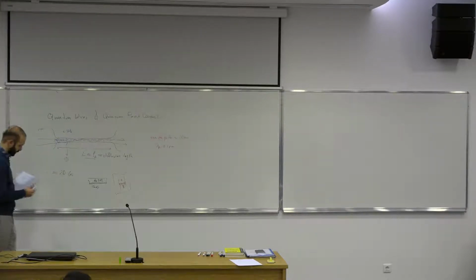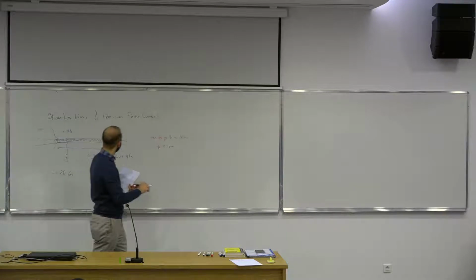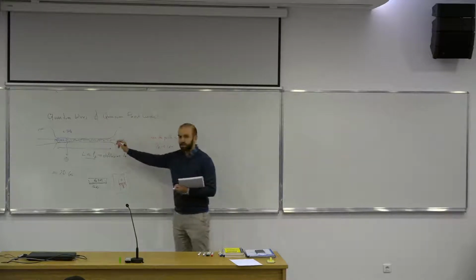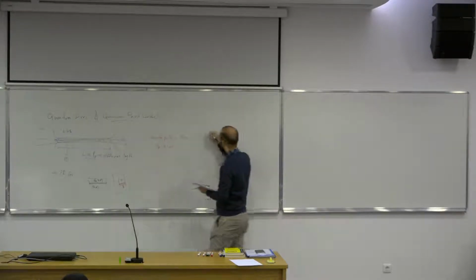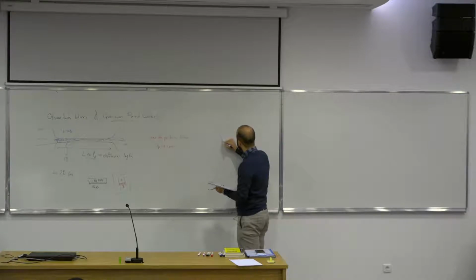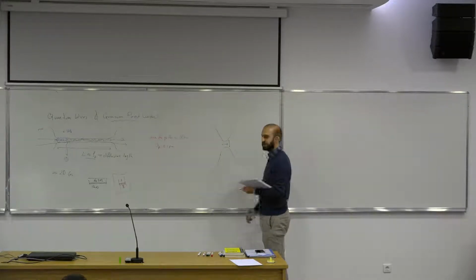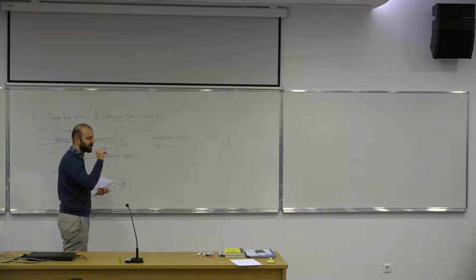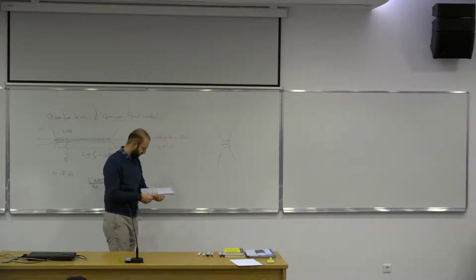So another object that I'm going to talk about is quantum point contacts. That's very relevant to sending electrons into a quantum wire. Actually, we are going to spend most of our time discussing quantum point contacts. And the idea there is you have a very narrow constriction, okay? So the width and perhaps the length of this channel is, again, comparable to the diffusion length. So we are talking about a very narrow channel that electrons can pass through.